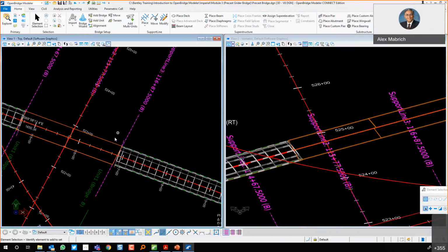Is there a way to make the structural deck thickness different than the pour deck thickness? Well, for the purpose of geometry, I would say here is the full deck, right? Because you want to report deck elevations there. But also remember that when you go into design with LEAP, there is an option to do sacrificial thickness and then the actual change thickness of your structural analysis there on design, right? So that's what you mean by the sacrificial wear, right?